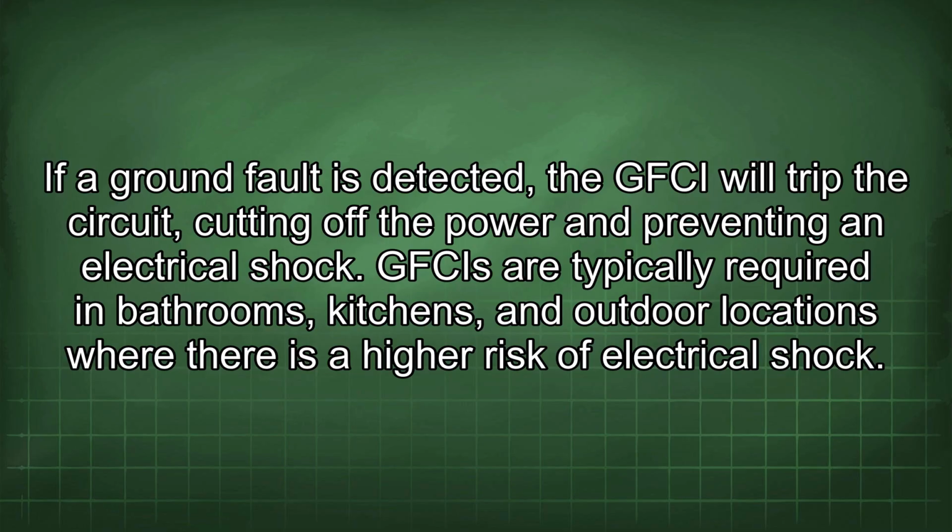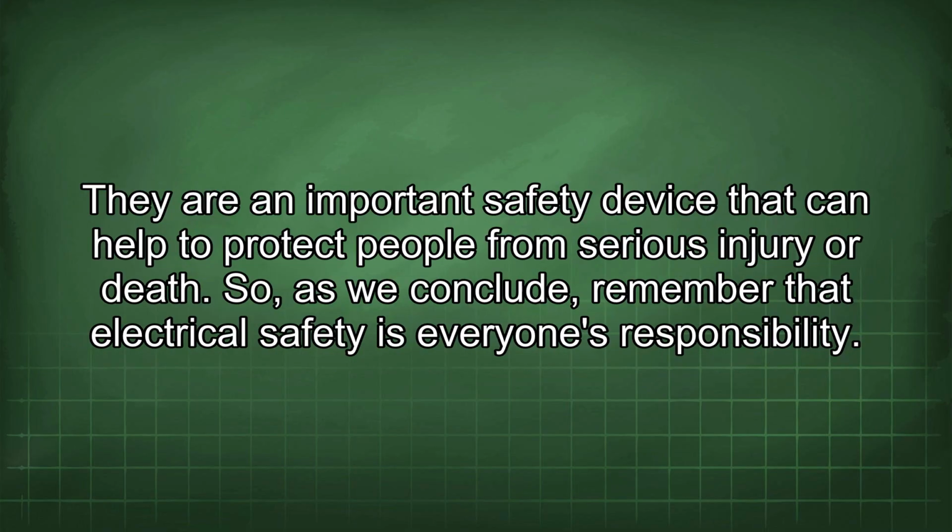If a ground fault is detected, the GFCI will trip the circuit, cutting off the power and preventing an electrical shock. GFCIs are typically required in bathrooms, kitchens, and outdoor locations where there is a higher risk of electrical shock. They are an important safety device that can help to protect people from serious injury or death.